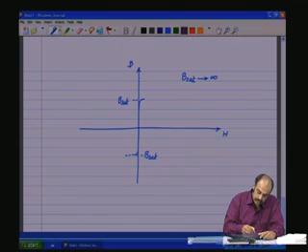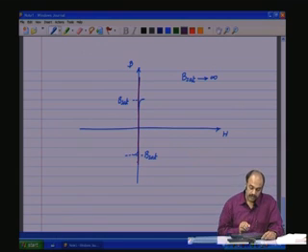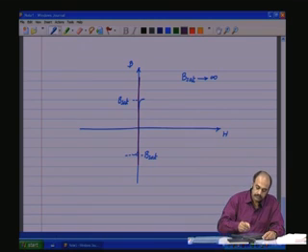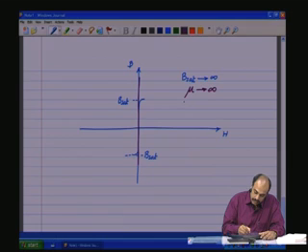with a magnetization curve which is the vertical axis itself. So, a magnetization curve which is the vertical axis implies B sat is infinity, mu tends to infinity, permeability tends to infinity, hysteresis loss tends to 0.